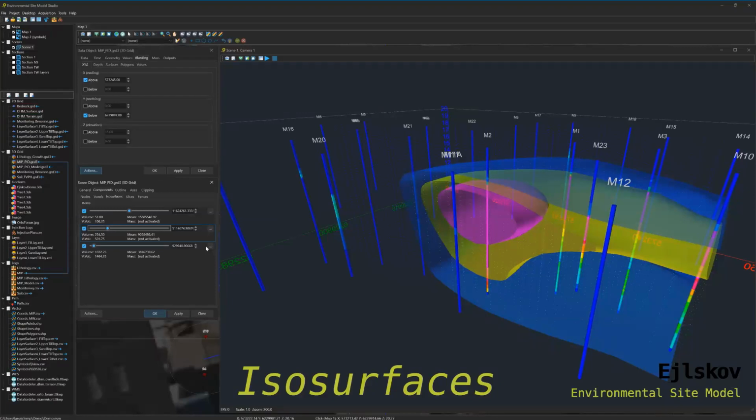So we would focus on the use of the MIP, because the MIP is also fairly powerful in identifying plume conditions, and work more on groundwater data solely. So create a lot of cluster wells that can help us in defining where we need the PRB to be more heavily injected, and where we can start to phase out the injections as we reach the boundary of the plumes.